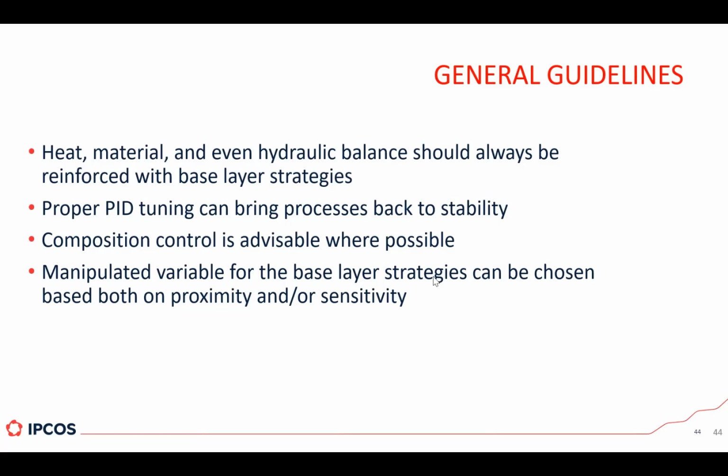And then, just as we mentioned in the previous example, the manipulated variable for the base layer strategies can be chosen based on both proximity, which is the initial instinct, but also based on sensitivity, if conditions allow you to.